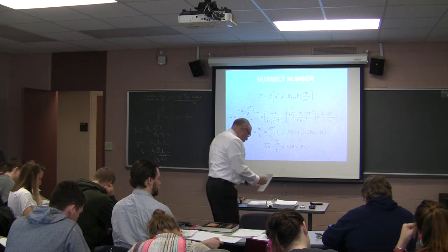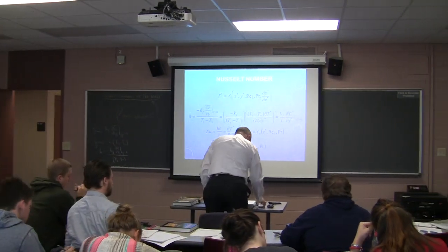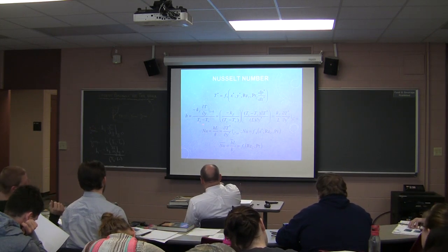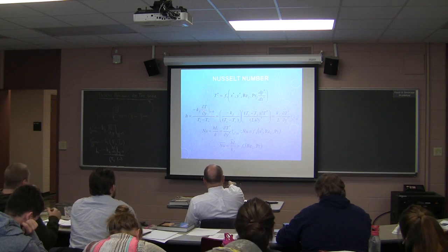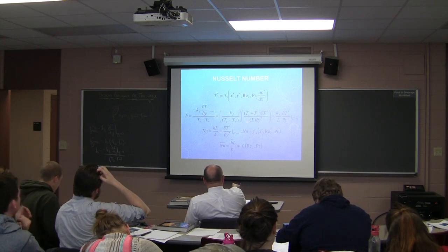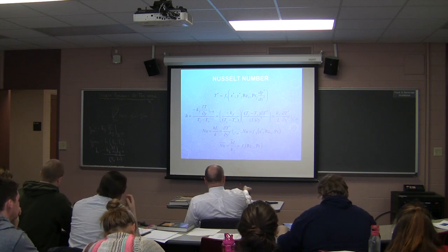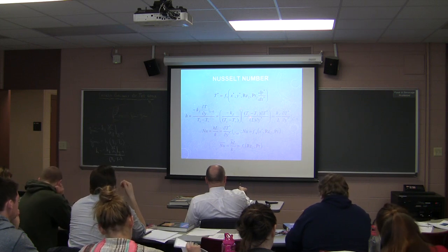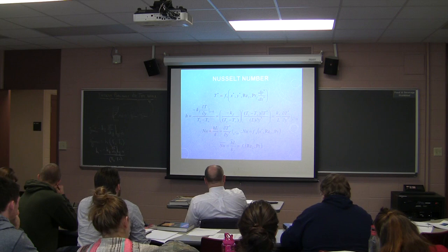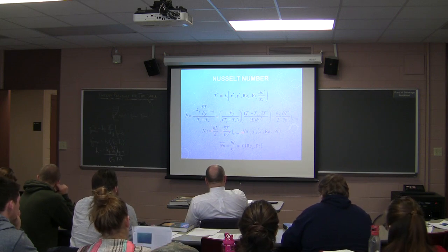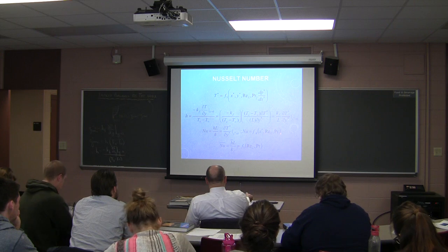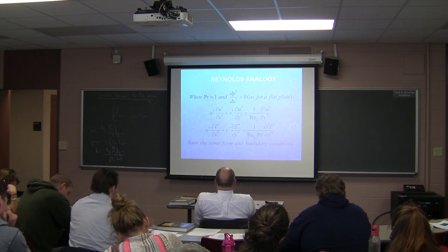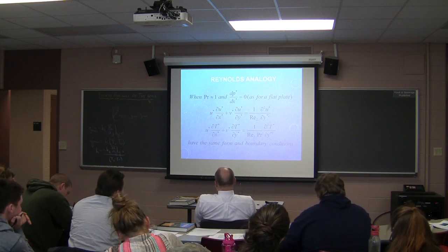Okay, trying to conclude our discussion here. So that's what this says right here. This is your energy balance at the wall. So if we then substitute in these terms in terms of our similarity parameters, we end up with this result right here. Uncharacteristically, he puts in everything. And then over here, the Nusselt number then can be expressed in terms of the function of x star, the Reynolds number, and the Prandtl number, as you can see here down here. Now, conclude today's class with this thought.